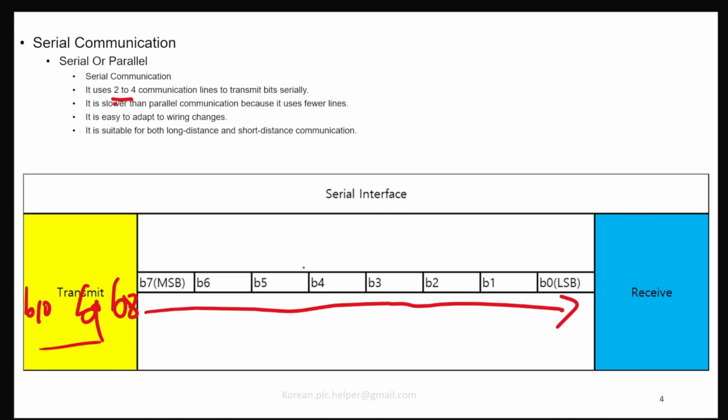High-speed communication is important in some factory automation applications. However, in typical serial communication applications, flexibility and expandability can be just as important as communication speed. This is because the communication system must be able to respond to changes such as equipment modifications and additional data requirements.